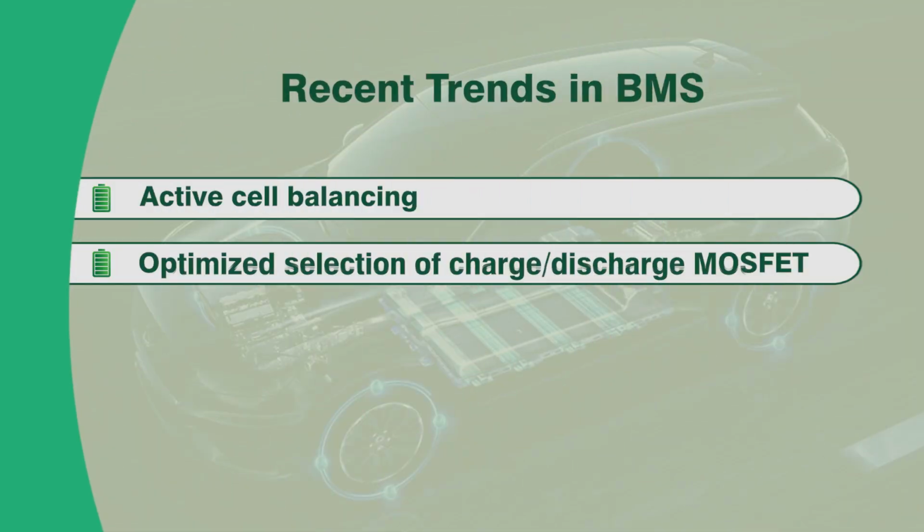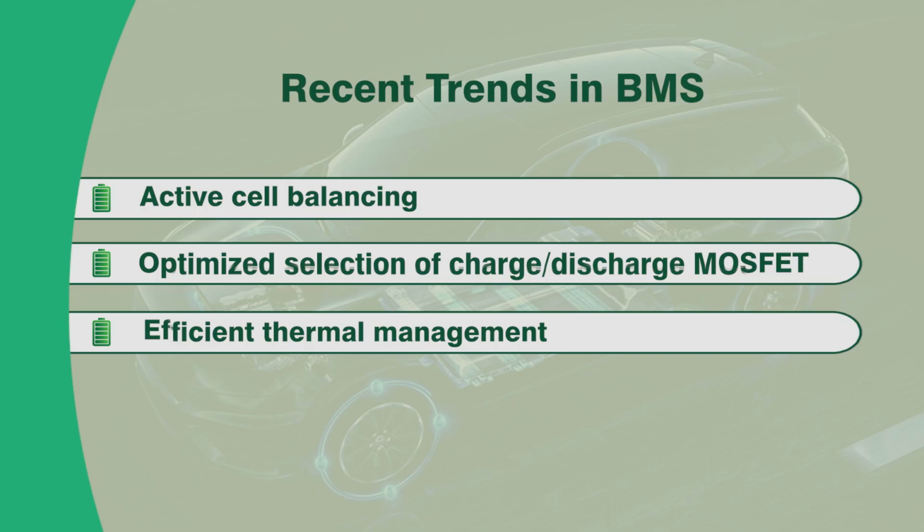You have to ensure the chosen gate driver and MOSFET are appropriate for your application, considering the current, voltage and other parameters. You have to select and design your gate driver circuit such that it has minimum EMI on the overall BMS, in order to get the different compliances associated with the EV battery packs. The next important parameter having a good research gap is efficient thermal management.